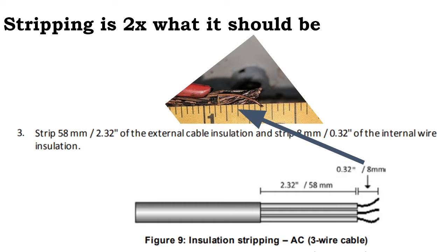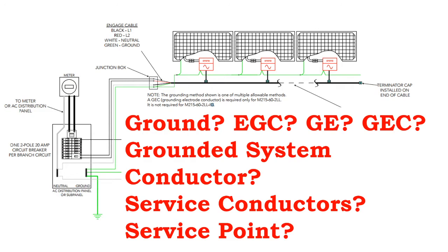So here in the installation manual, we have very specific instructions about how much of the stripping to take off, and that's going to vary from inverter to inverter, and at different ports on the inverter, it could change as well.